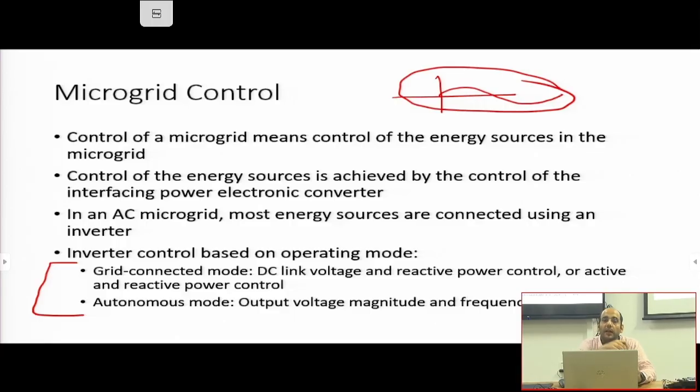So that regulation of the voltage now is the responsibility of the inverter. While we just talked about when it's connected to the grid, it is like a current source injecting a current to change the P and Q. Now it will behave like a voltage source to regulate the voltage supplied to the load. That is called grid forming mode. The inverter forms the grid.